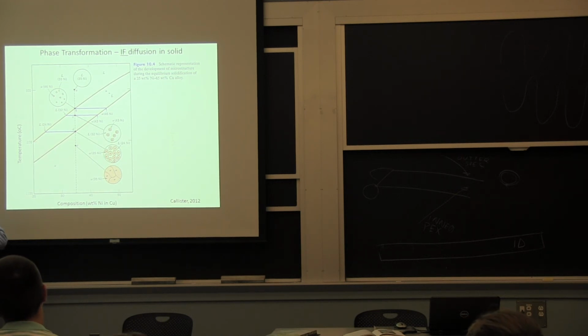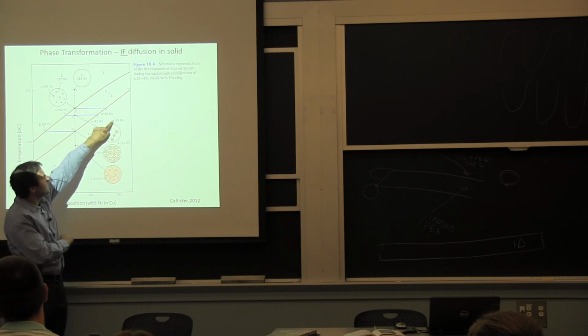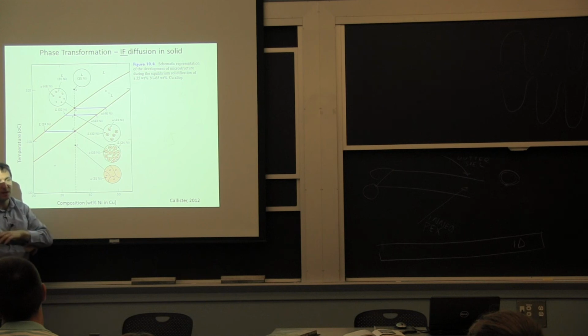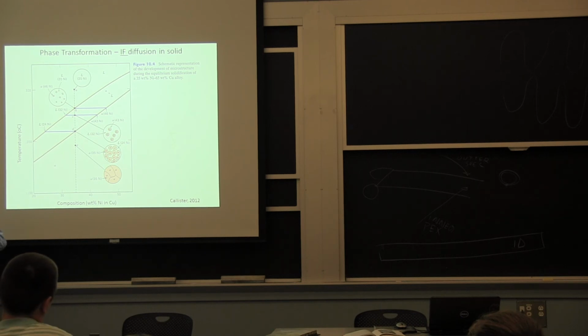At ambient temperature. So at those temperatures we're dealing with here for the solidification, what's going to happen, generally there'll be some diffusion in the liquid, but in the crystal, the first piece that's formed as 43 here will stay at 43 in the cooling process. But I'm essentially telling you that you could trust the phase diagram if you were willing to wait until everything comes back to the same temperature.